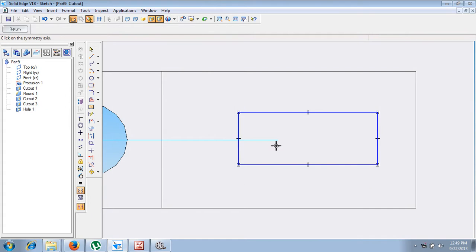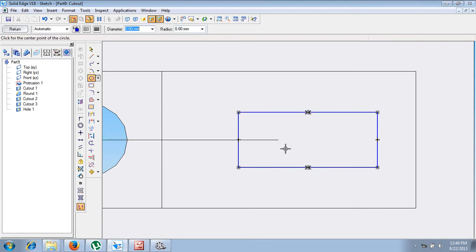After that, once again use a symmetric relationship. First you are supposed to select the axis, then the elements to be symmetrical. Then make use of a command called circle by center point. With respect to the midpoint of the shortest distance, select the center and the radius, the radius value being the larger line endpoint like this. Similarly, repeat the circle here also in this fashion.